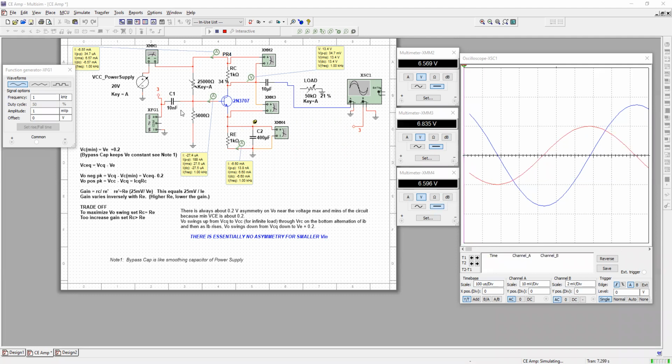There's less impedance here, and more of the voltage is passed on to the voltage divider resistor. So let's see what would happen. The other thing that we can do is increase our frequency. That has the same effect of reducing the impedance of the capacitor. So let's do both things.